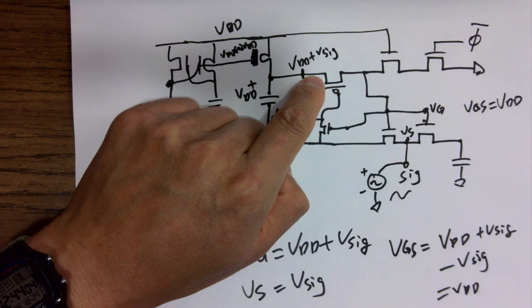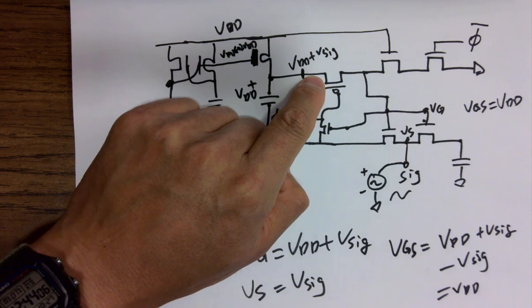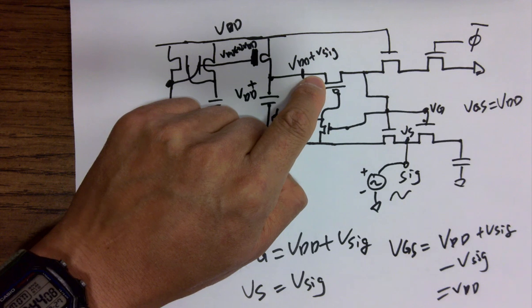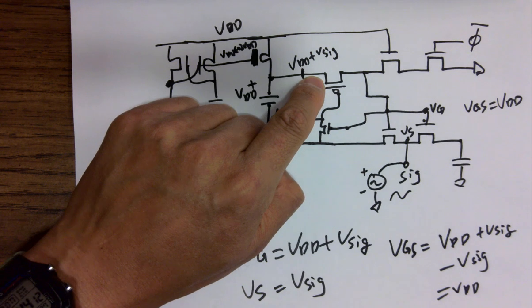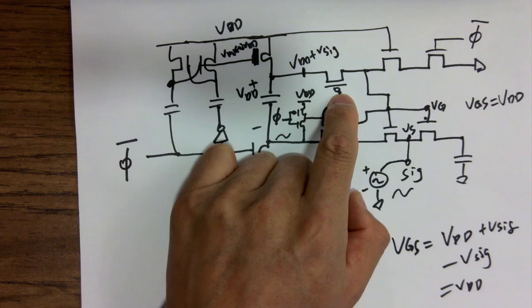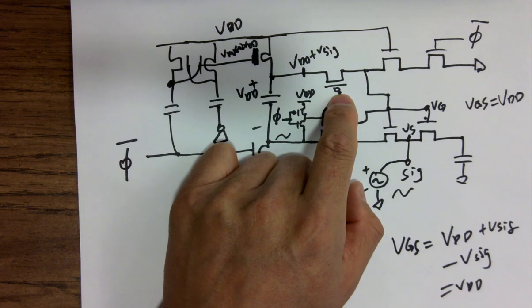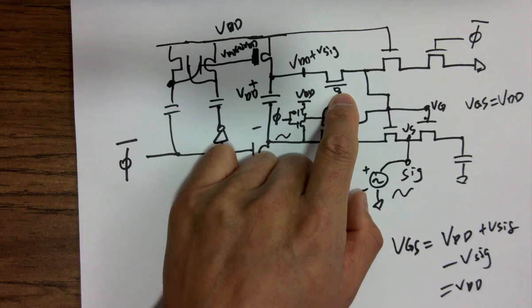It always happens, right? If it's subtracting, it's pulling, then it could be less than VDD. But there will be a chance that it will be added to VDD, so it becomes larger than VDD. So this PMOS needs what? Its own well. So in schematic design, what do you want to do?